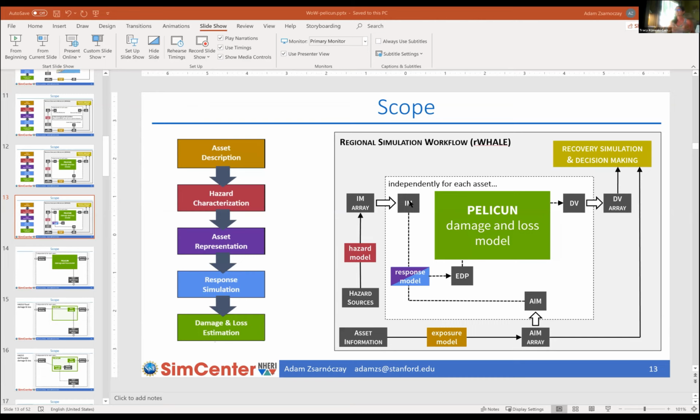The second is, do we have meaningful hazard simulations for these areas, which would again require having bathymetry and topography, land use, land cover, all the things you need to drive that wind field or storm surge in that area. For the Caribbean, and knowing where Maria's from, some of that already exists, at least hindcast results for Maria that are available, including the ARA wind fields, which are in DesignSafe now, and some of the ADCIRC simulations, I believe, are also posted.